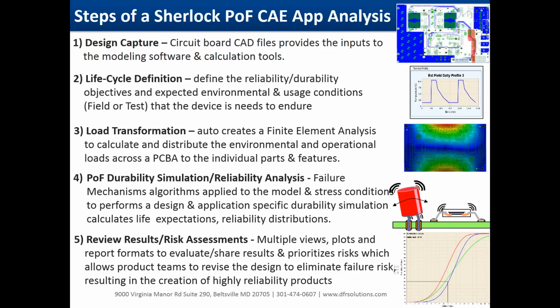And you would then just treat the simulation failure result reports as you would your physical test incident reports. And you say, oh, this part is failing for thermal cycling and this part is failing for vibration or whatever have you. And then you can go in and figure out ways to optimize the design to remove its susceptibility to failure.